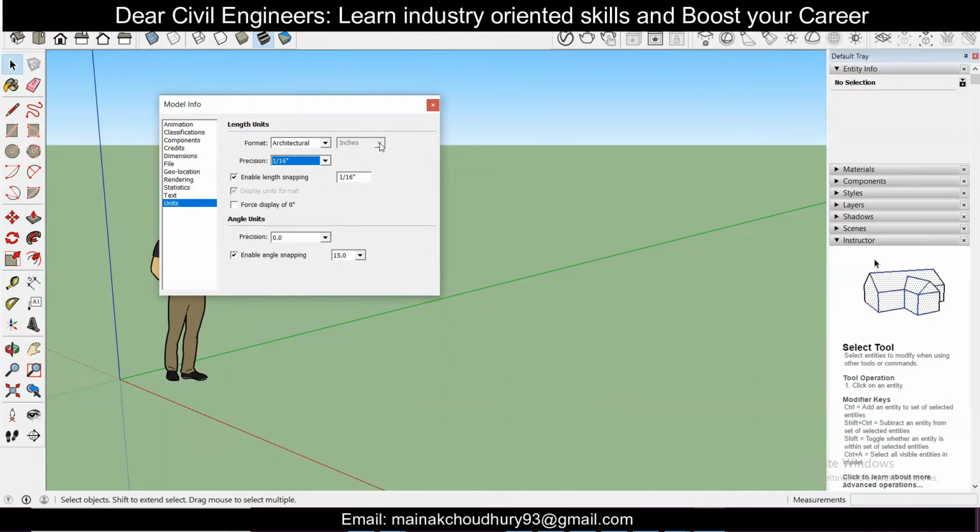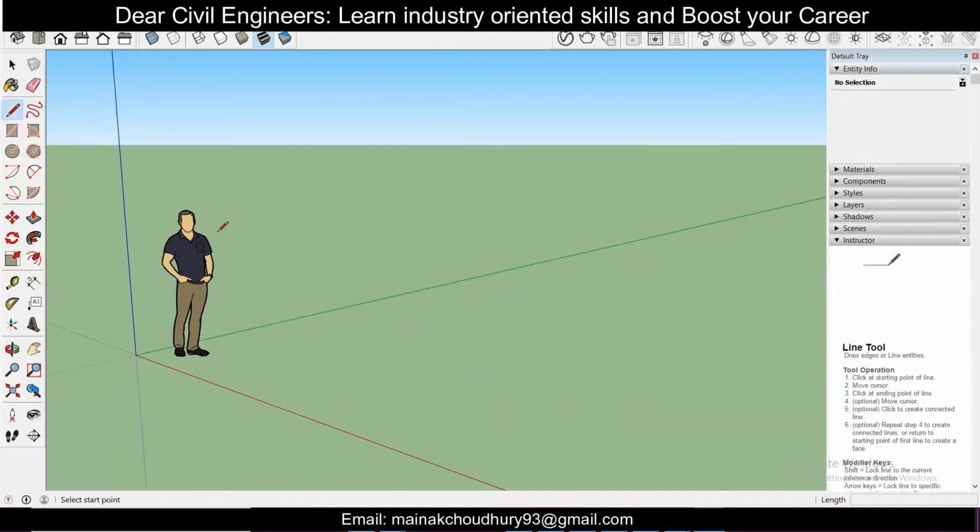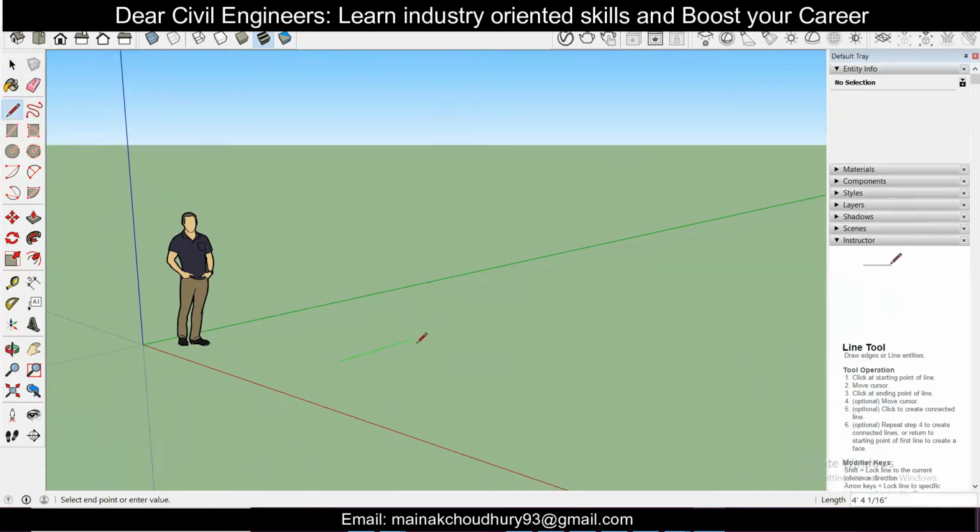Suppose this is in inches here, so I am just taking this simple line here and clicking on here, and as you can see, this freely rotates. And along the red line, when it snaps on the red line, I'm just entering a value. You can note this in this particular thing, the length. I'm entering a value, say 120, enter. I've not entered any unit, I've just pressed 120, enter.